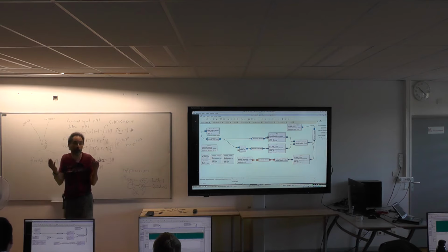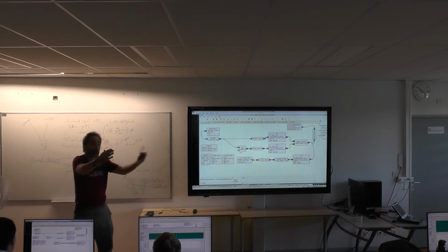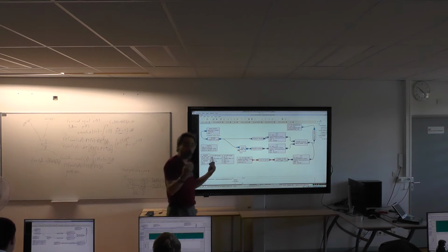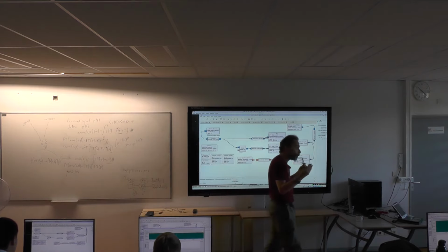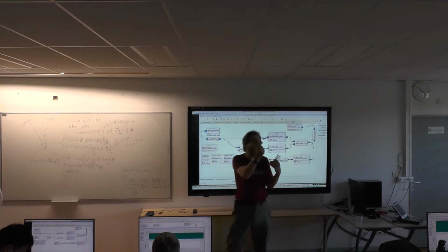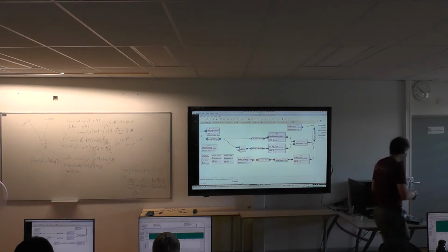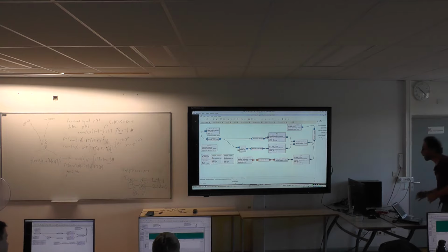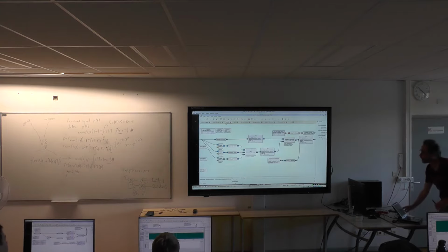Or if I come back to my noise radar example, I broadcast a signal, I've got multiple targets, and even though I want to detect all the targets that backscattered energy, I only need to take one Fourier transform because the Fourier transform is linear. And I don't need to run as many correlators as there are targets.